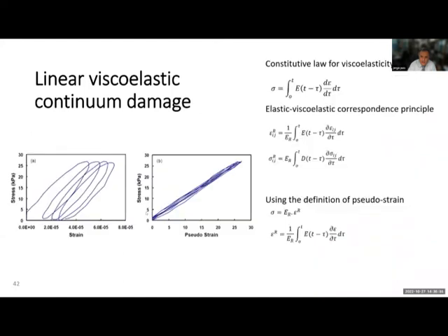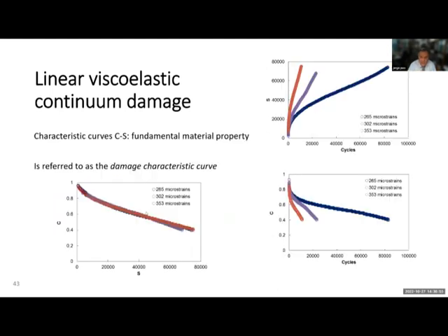And that is amazing, because with this analysis we can convert viscoelastic problems into linear problems by defining the pseudo stiffness of the materials and the damage parameter. The evolution of the damage and the pseudo stiffness follows the trend that we have on the right-hand side.